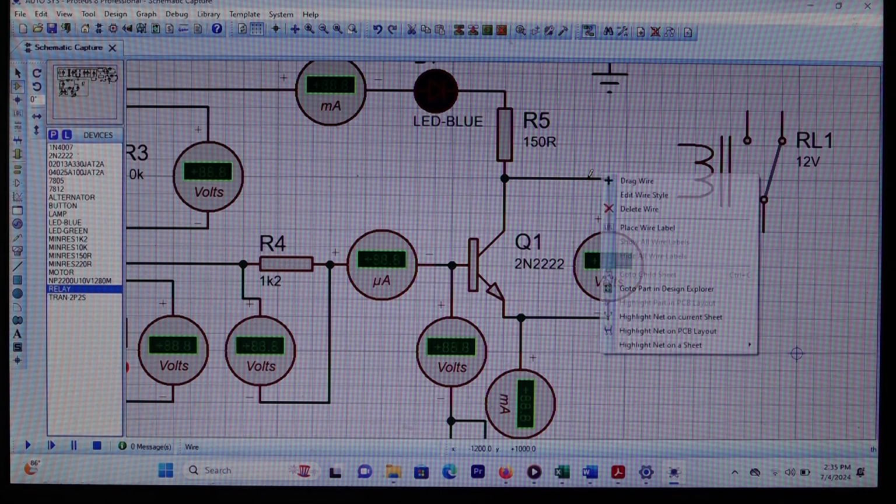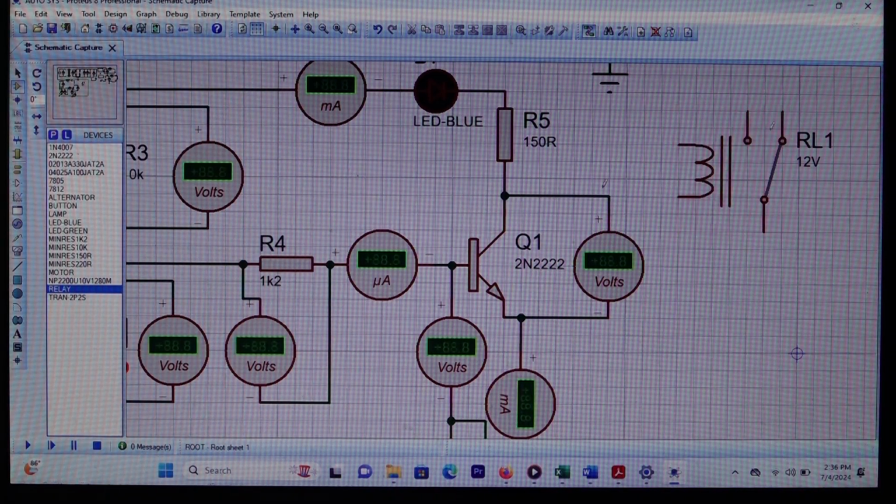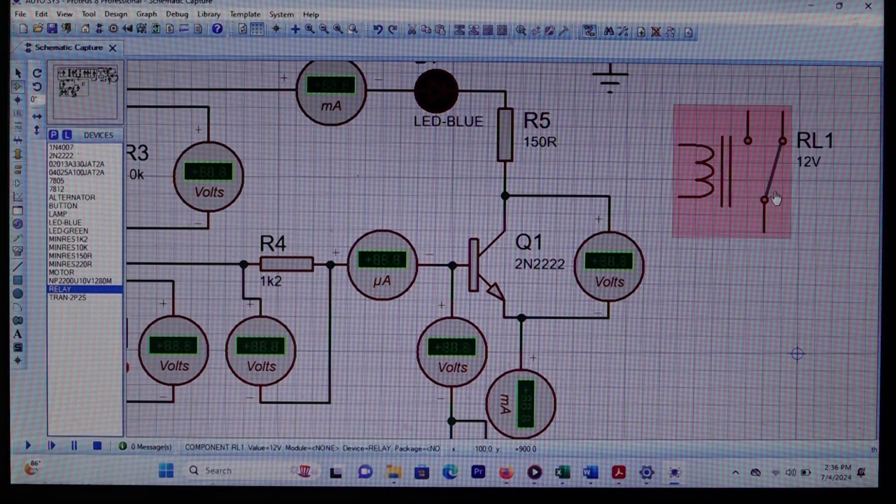We're going to connect it with the collector terminal of this transistor. But before we connect this relay switch, it's better also to discuss one of the theoretical concepts of the load line. In the concept of load line, a load line presents three regions of the bipolar junction transistor. The first region is called the saturation region. The second one is called the active region. The third one is called the cutoff region. Are we together?